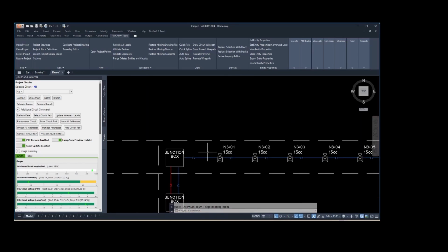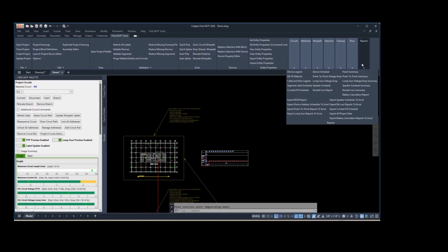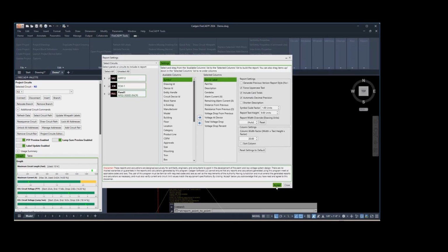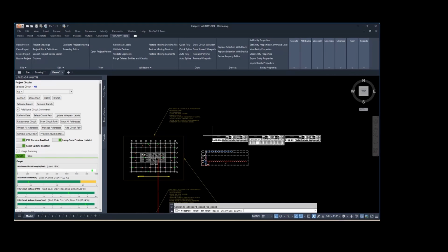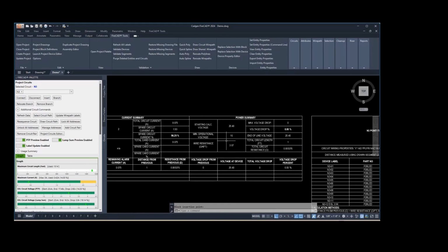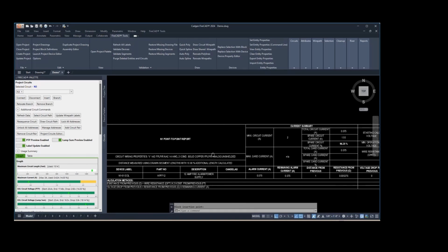Here's your NAC circuit on the 3rd floor. Here's some of the other things that are automatically done. We do a riser automatically. You saw that. How about a point-to-point voltage drop? Click accept. And we're probably going to get an issue here, which is going to be a cell. No, maybe not. With an end-of-line value that's not correct. And I'll show you what that issue is.